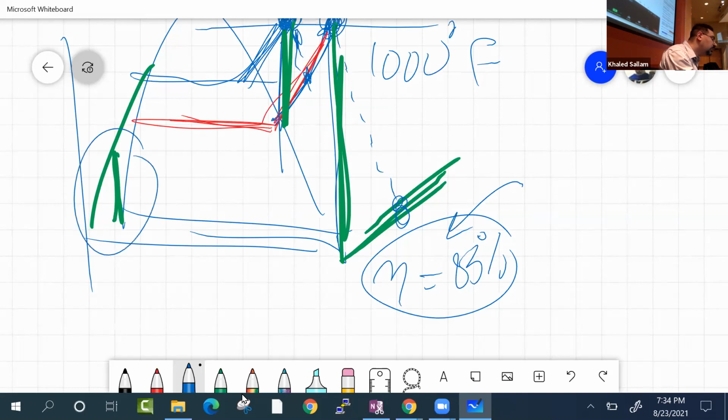This would be true for the pump. We are assuming an isentropic pump, so you can easily say, well, let me assume 50% pump efficiency. And that is horrible. Not really that horrible, actually. It's like 50 is okay. So assuming 50% pump efficiency, how does this change my eta thermal? And you do the calculation for the whole thing. What does the whole thing mean? You're just going to change this point. This point will be a little bit up. And how does this change things?